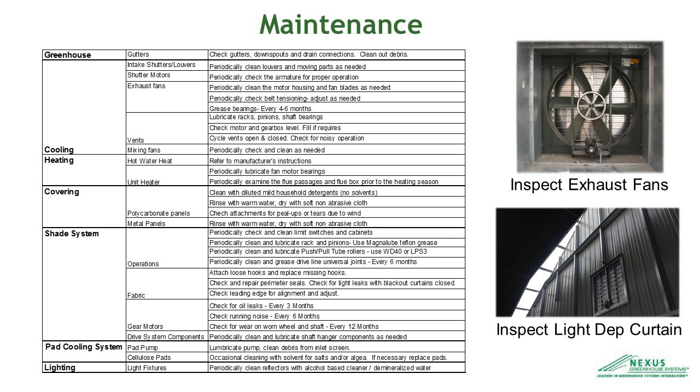And then you have your mixing fans, which occasionally you need to clean as well because they can get dusty. Your heating equipment, you have to look at your manufacturer's instructions, which we provide with the equipment that we supply. And on occasion, you'll want to grease the bearings and also clean the fans. So you'll do this before every major heating season. So in the fall, you'll kind of go through and you'll check on all your unit heaters and all your equipment. If you have a boiler system, you'll refer to the manual.